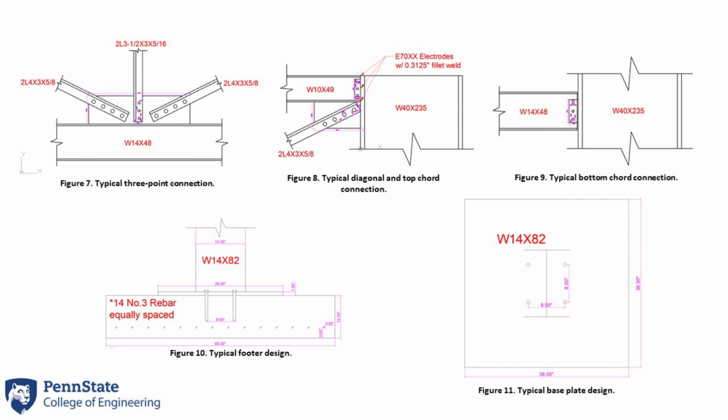From these footing designs, the team then created base plate design sheets to be used for each typical footing and column. Lastly, the team created a typical connection calculation sheet that would be used to design both fixed and pin connections at different points in the system. From this, the team was then able to make the material estimate that was shown in slide 1 and gives the company a rough idea of the material amount and therefore cost.